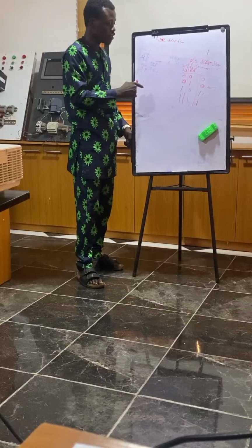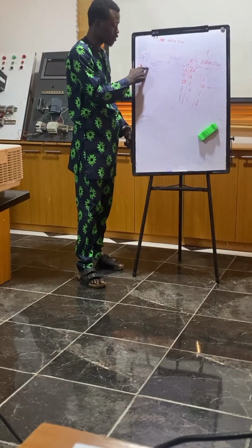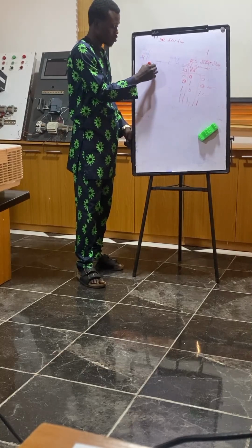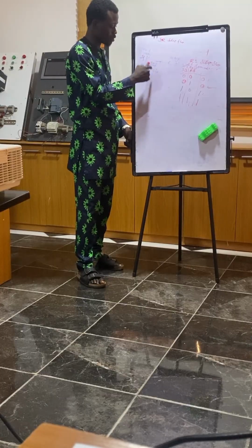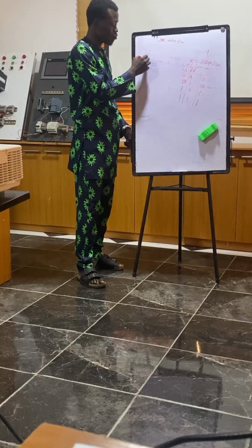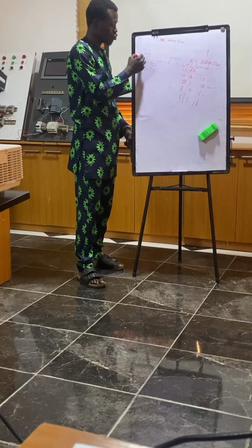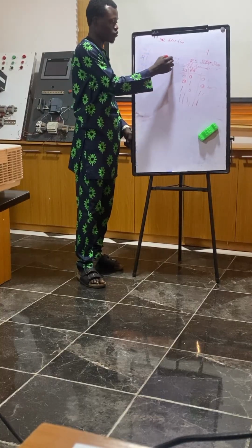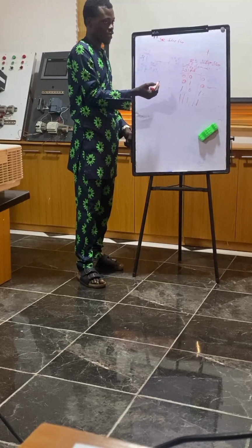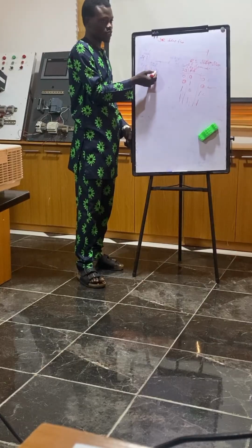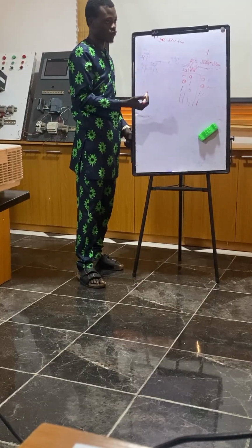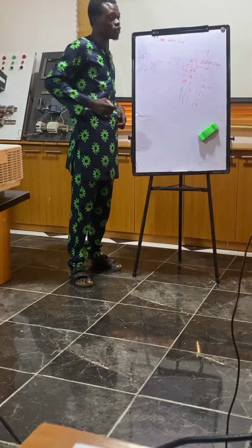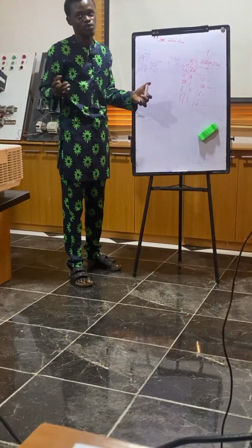So the last one is such that when the two of them are pressed, okay, 1, 1, 1, 0. So 1, 1 is such that a signal of 1 flows directly to this guy. Even though this one inverts this to 0, it's none of anybody's business. So for that reason, this also passed the test of the RS flip-flop. So that is it.